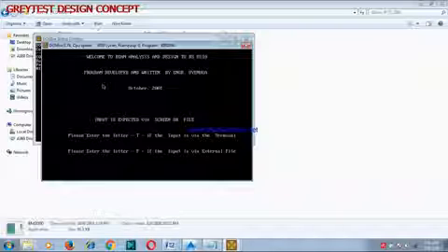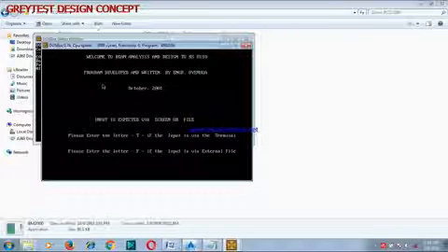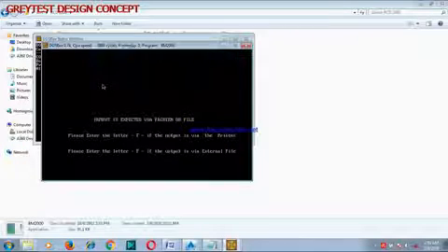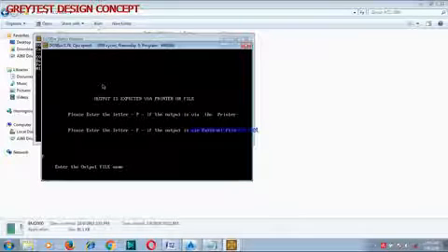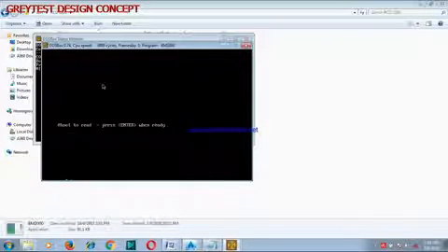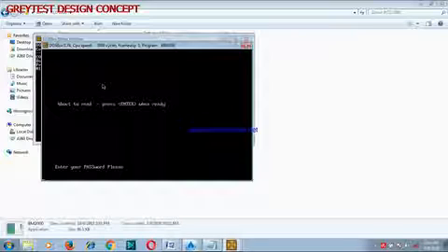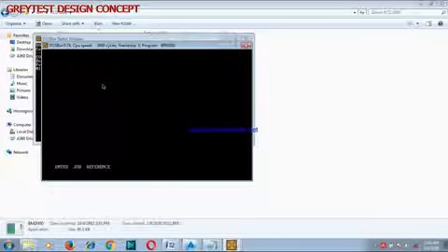Okay, the next thing you do is to type T, enter, F, enter, output name, let's say beam design, enter, no password, job reference is just job number, /job/002.